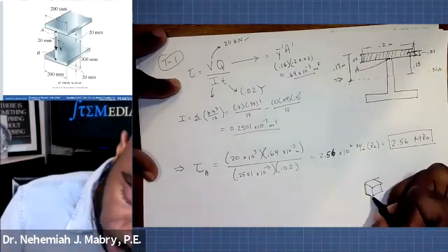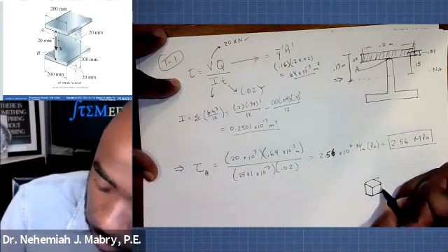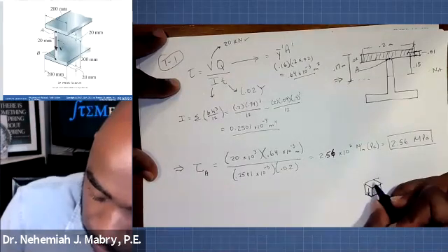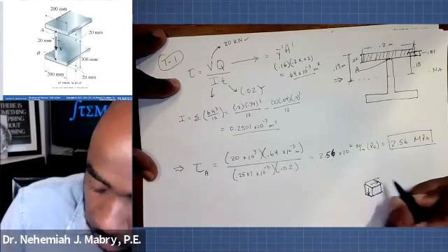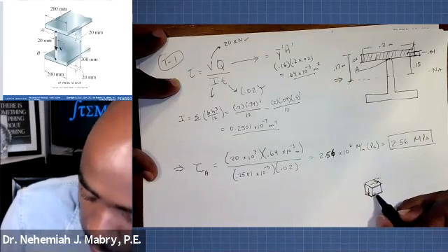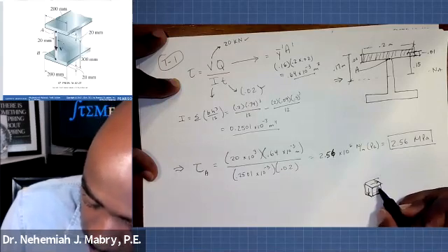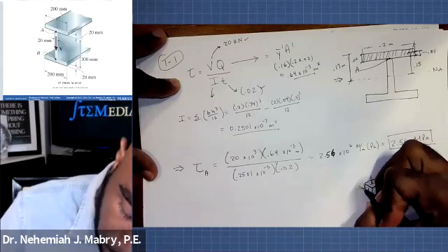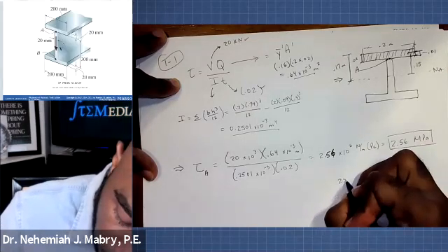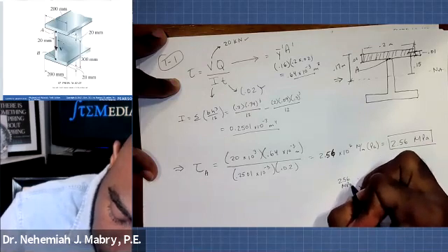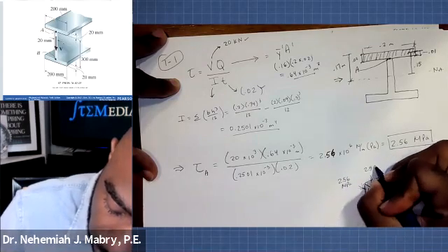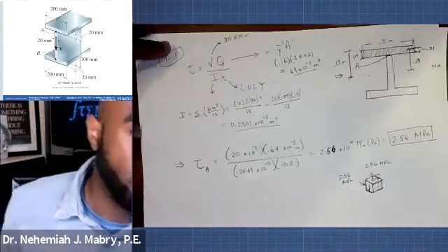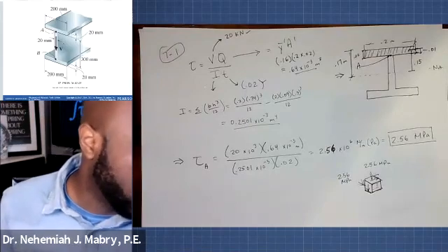And basically on this 3D box, we have a shear going down here, shear going there. Underneath it, obviously, we'll have another shear, and on this side, we have another shear. All it's saying is that at this volume block, this shear is 2.56 MPa, and this one here is 2.56 MPa. That's all it means by indicate the shear stress components on the volume element located at this point.